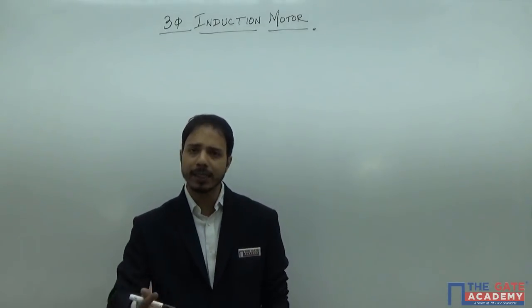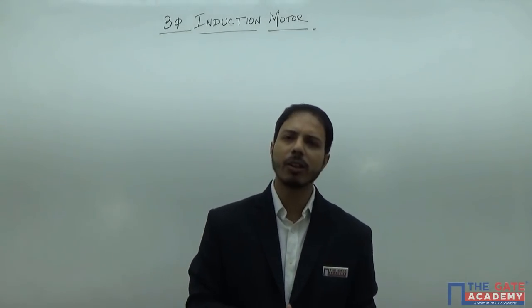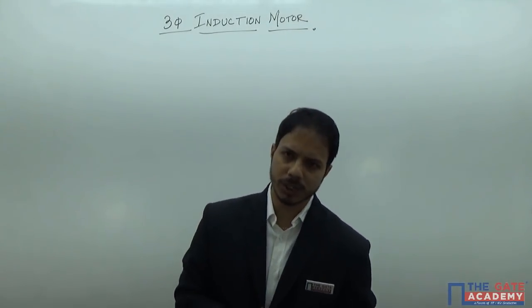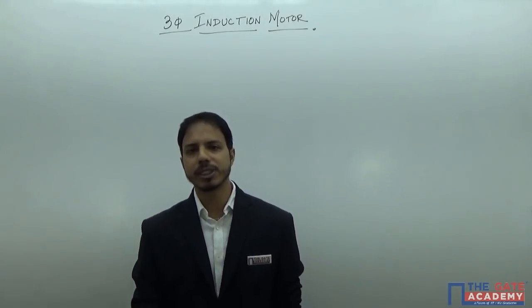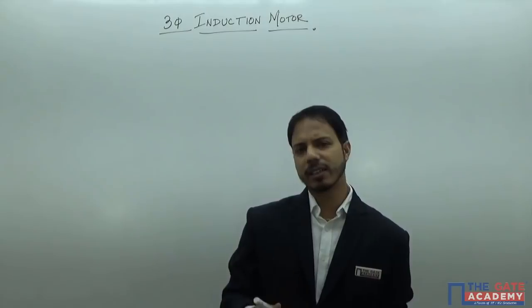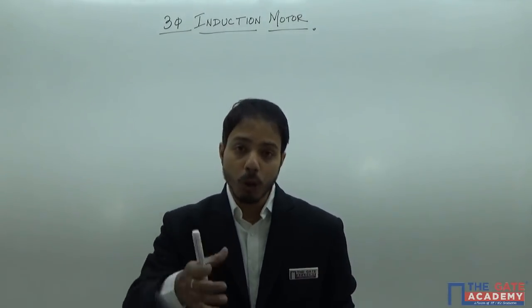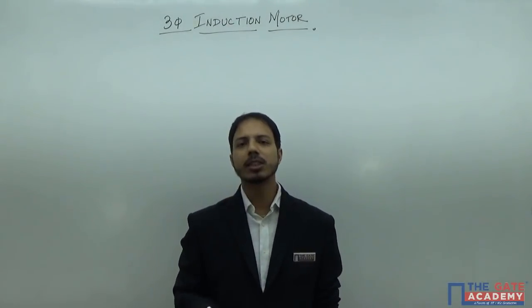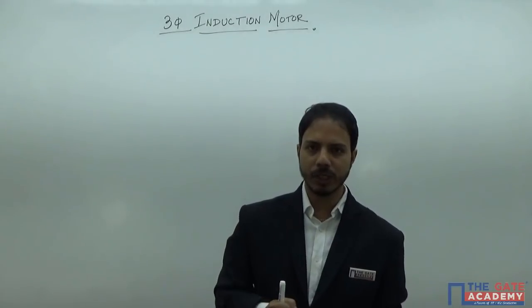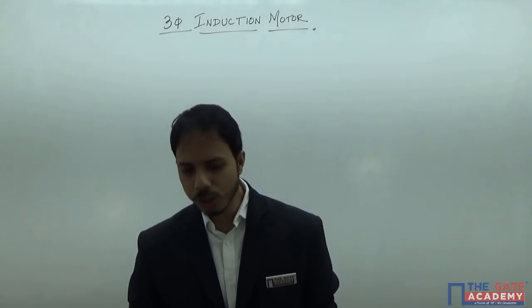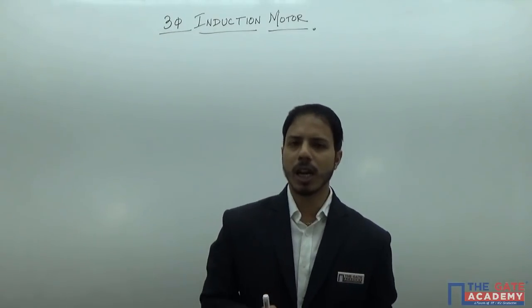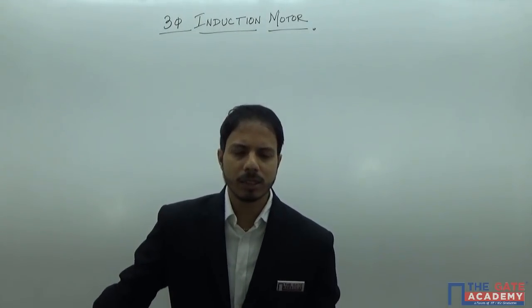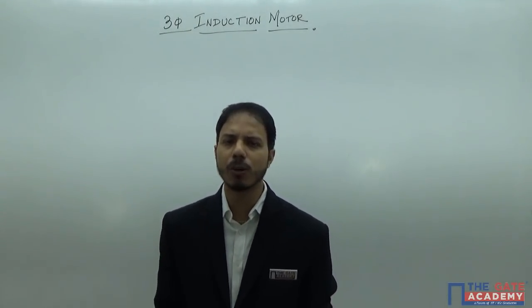Whereas in GATE, if you see all the questions throughout the years, they will mention that you can take the best approximation circuit, or they will even write in the question to neglect the stator impedance, that is, the stator resistance and stator reactance. The moment you neglect the drop in the stator, the analysis becomes really, really easy for you. My effort will be to make you realize these approximations. So let us see how we can do that.